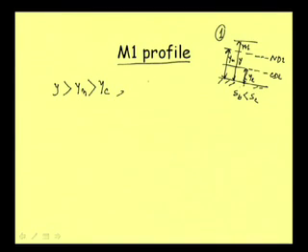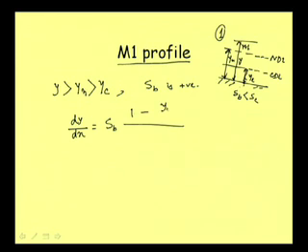Now, if we use this equation and, of course, another parameter SB, the bed slope. Mild slope means SB is positive, SB is positive. Okay. So, what is our relation that we are getting is dy dx is equal to SB into 1 minus yn by y whole cube divided by 1 minus yc by y whole cube. This is the relation.